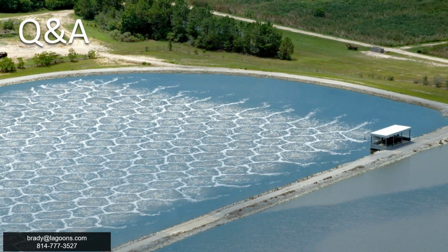Is it true that turbo blowers are not very good for temperature swings as well as summer and winter operation in Canada? That's going to be very dependent on the turbo blower. I know some manufacturers have temperature conditioning devices to temper the temperature coming into the blower. I also know that turbo blowers generally are a bit more fickle. Not all manufacturers of turbo blowers allow you to put them outside. So I think winter and summer operation has a big impact on where you put it. Do I put it outside or in a building? I can't speak specifically to temperature swings. I have not seen that issue.